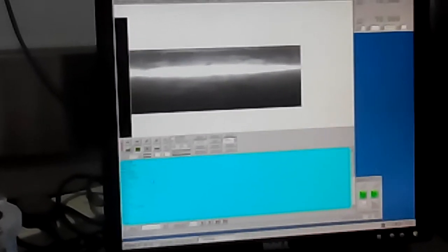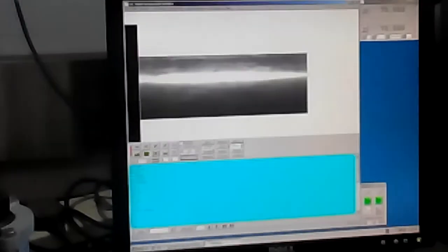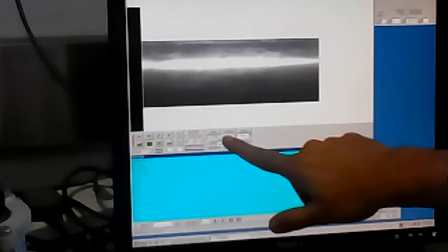Yes, once you enter your program here, you're going to type it here. You have to make sure that this program is correct. I just entered the sample program to show you. You're going to simulate this one. For simulating it, you have to press Auto. You can see this Auto is there. Then in this window there is a Cycle Start. Click on Cycle Start, and it will show how the program is going to run.